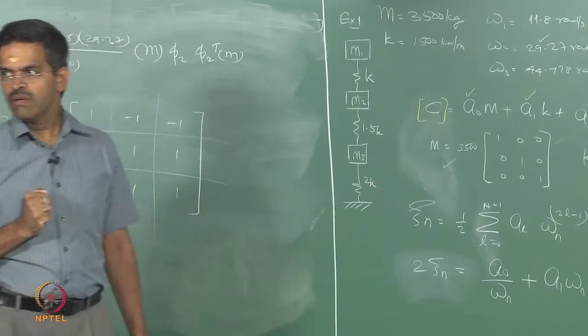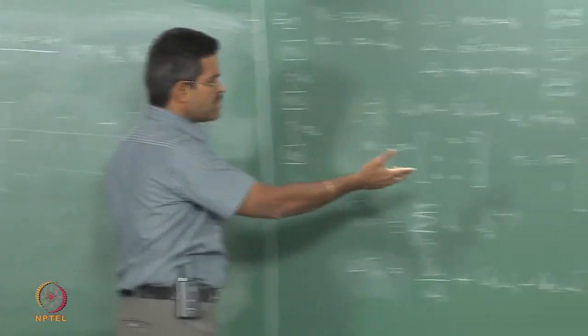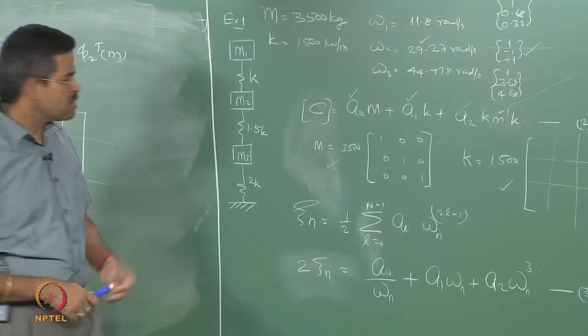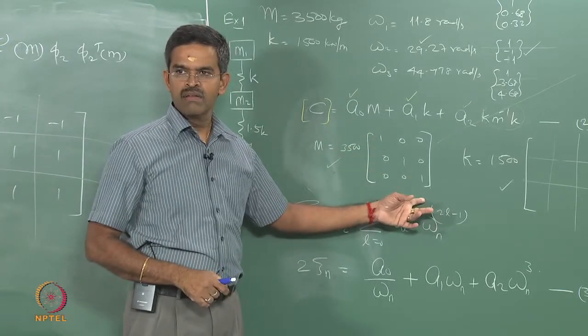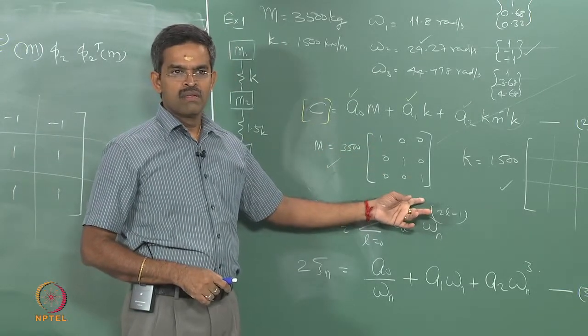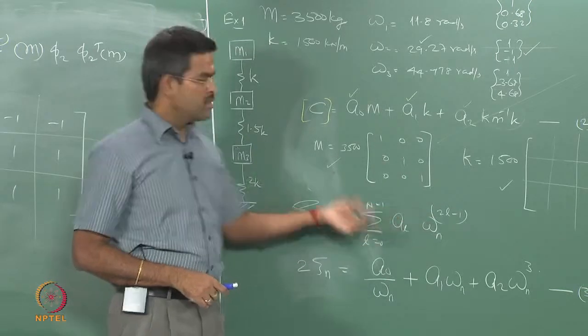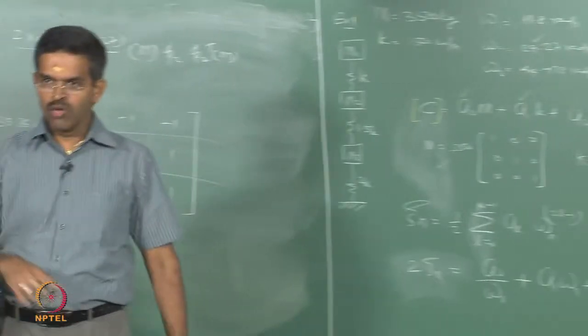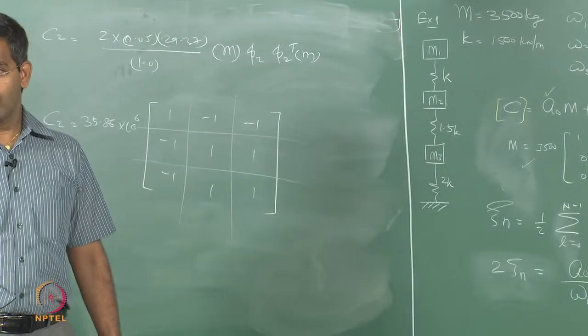Sorry? There is no stiffness matrix, the answer is not in the board. Because the mass matrix is diagonal here. The mass matrix is diagonal. It means displacements are measured at the lumped mass points. If you do not get the basics, we will be rounding only. Okay? We will not be able to get through the dynamics at all.